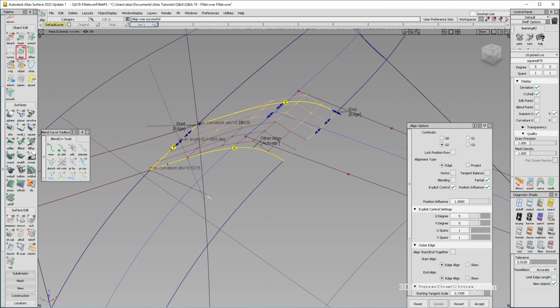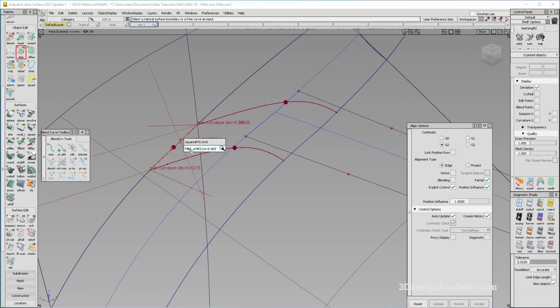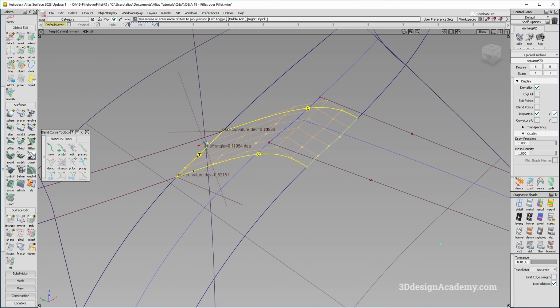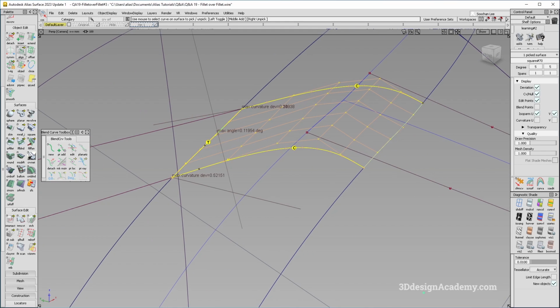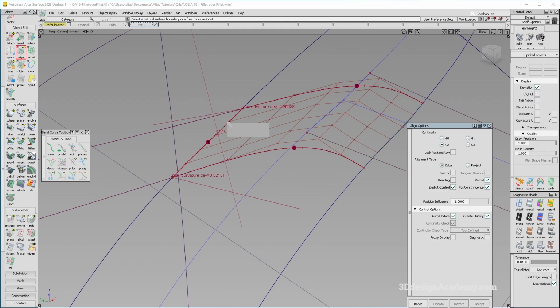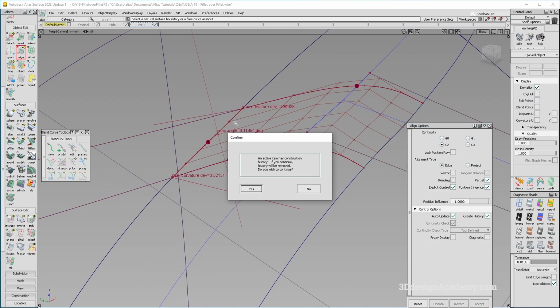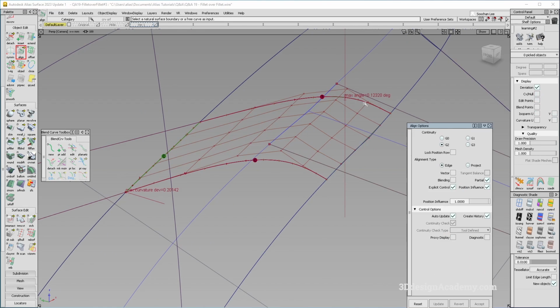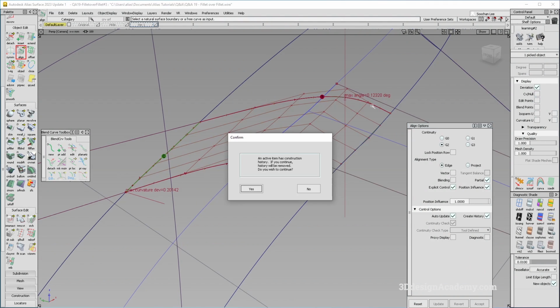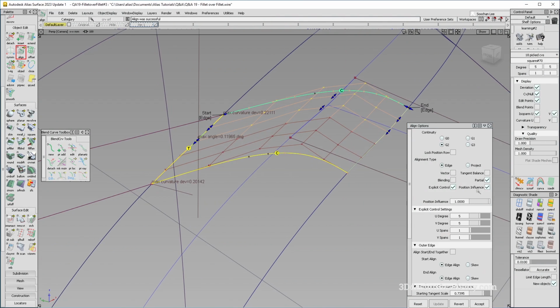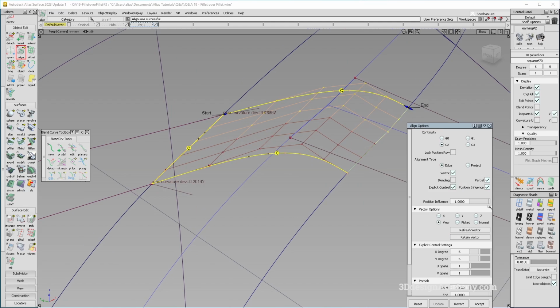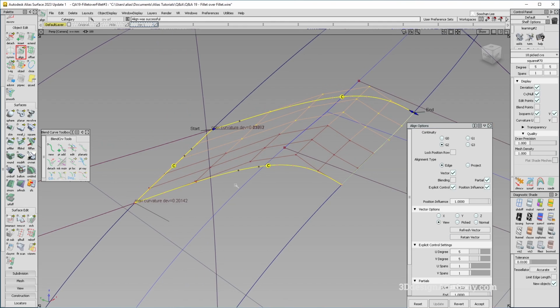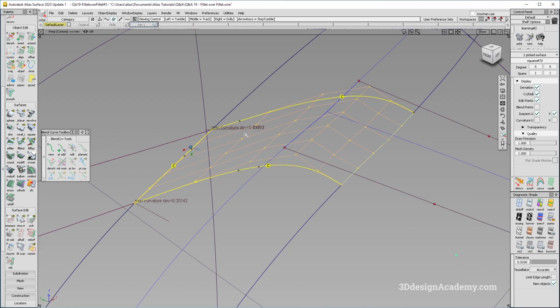Okay, so it looks like it's a very mixed bag. So I'm going to, let's see. I wonder if I align this one again. Okay, so I've got curvature there. Still failing tangency over here. So I'm just going to go around and see if alignment like this helps in any way. So it looks like view. Okay, so I've got curvature failure on this side and this side over here.